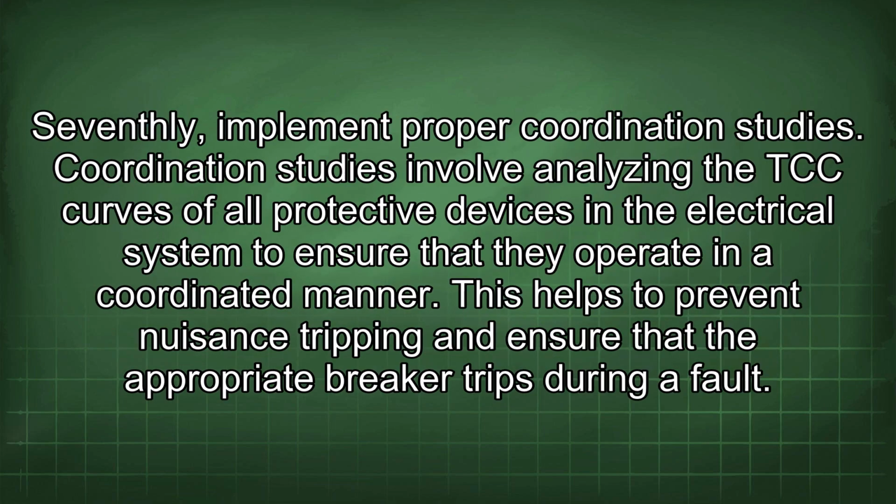Seventhly, implement proper coordination studies. Coordination studies involve analyzing the TCC curves of all protective devices in the electrical system to ensure that they operate in a coordinated manner. This helps to prevent nuisance tripping and ensure that the appropriate breaker trips during a fault.